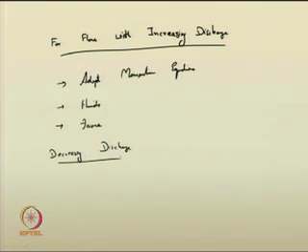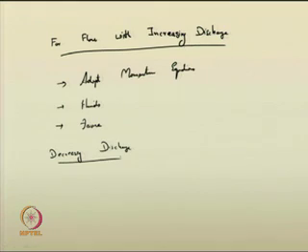you will see that they are mainly used for diversion flow problems, where flow diversions are required, especially in dams where you need to divert water to a particular canal. For such situations they are used. In such problems you will see the energy loss is not that significant, so that the energy principle cannot be applied.